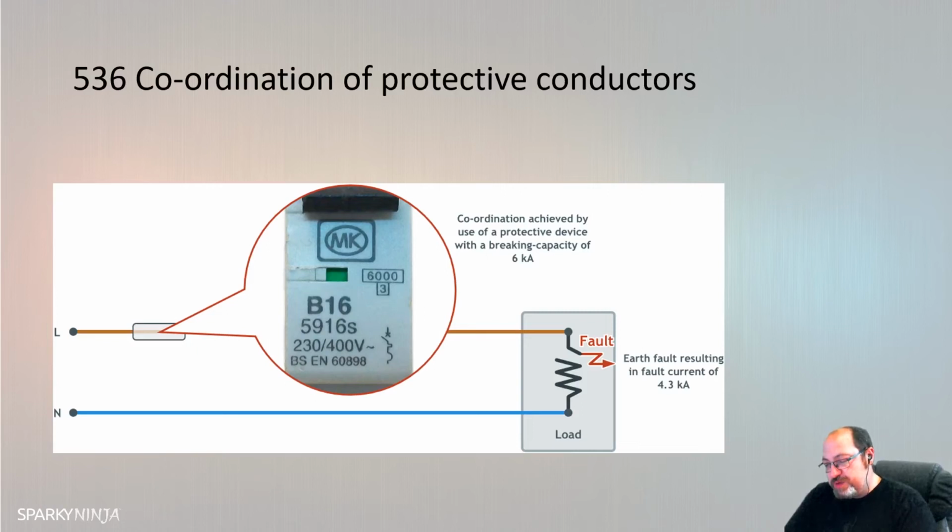Section 536 does not provide requirements for the selection of an electrical device alone, but provides requirements for the selection of electrical devices to achieve electrical coordination between them. The requirements also cover aspects of continuity of supply of the installation. So the coordination requirements for selecting electrical devices as covered by the following regulations: the mutual interaction between those devices shall be considered so that they do not adversely affect the safety of the installation. The coordination of the electrical devices considers the case of short circuit, overload and residual current. Aspects for coordination of electrical devices are selectivity, short circuit protection and overload protection.